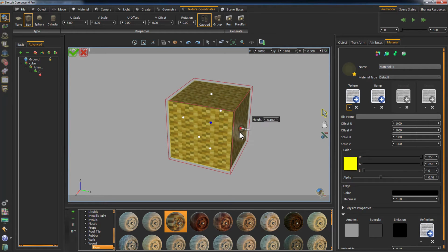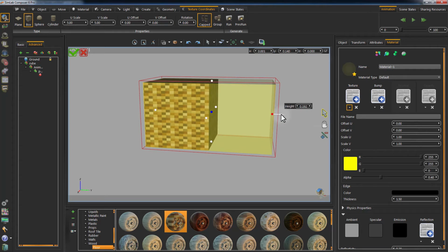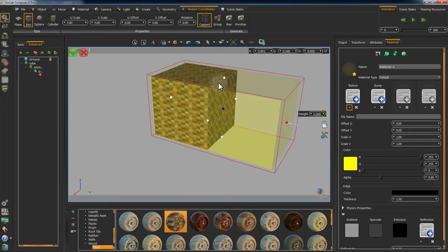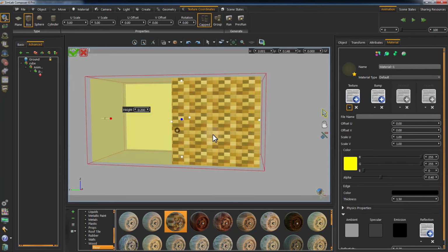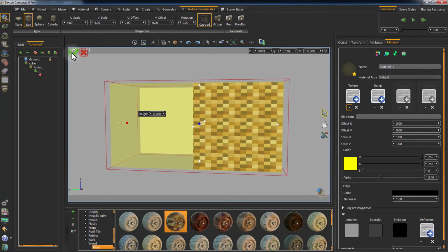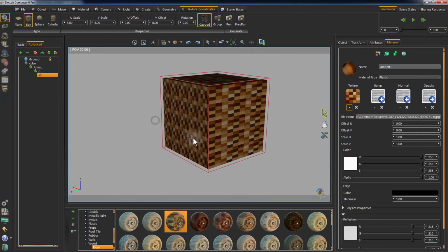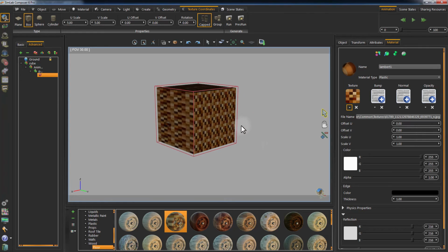Click on the white dot on the right side. An arrow will appear. Drag the arrow outwards to increase the size of the projection box in that direction. Now it has a height value of 0.2 instead of 0.1. Now if you apply the changes, you will see that the texture has a stretch factor of 2. All the sides affected by the modifications are stretched to double their original values, while the other sides remain the same.